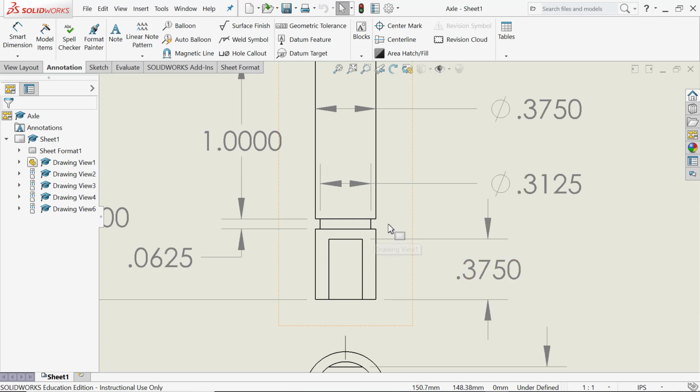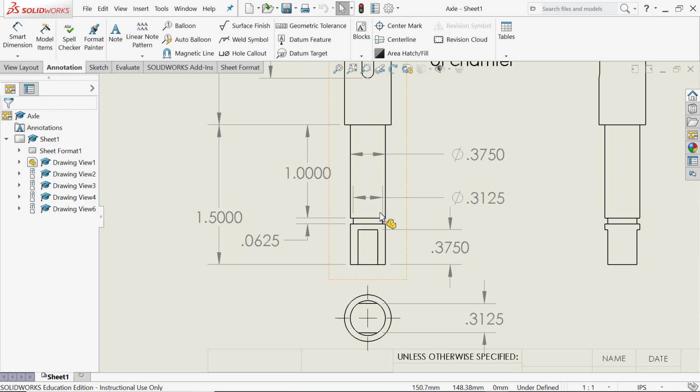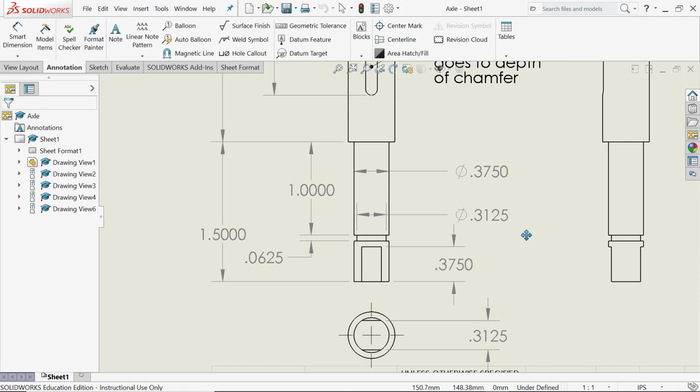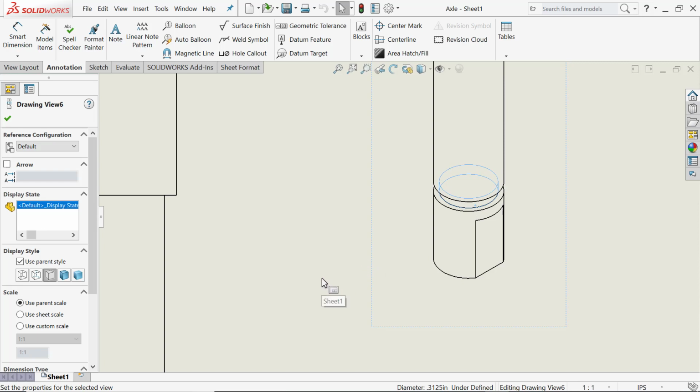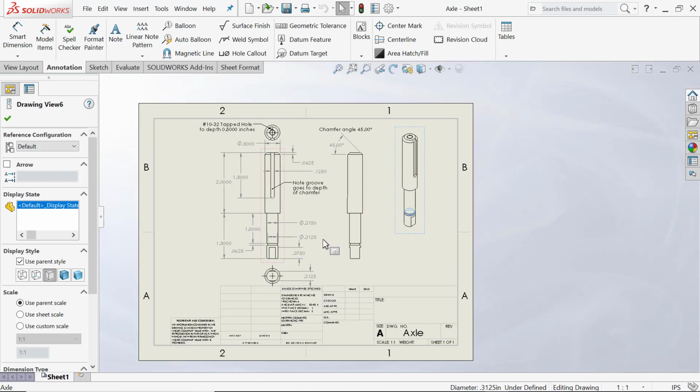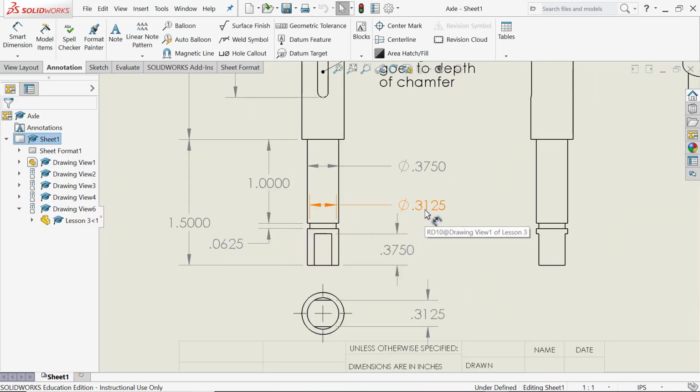And we're going to make that cut where the top edge of it is 1 inch from this transition here. The bottom edge is 0.0625 from that transition. And after we're done doing the cut, it will leave a cylindrical bit in there, this little cylindrical part right there. It'll leave that cylindrical part of a diameter 0.3125, which is 5/16, by the way.